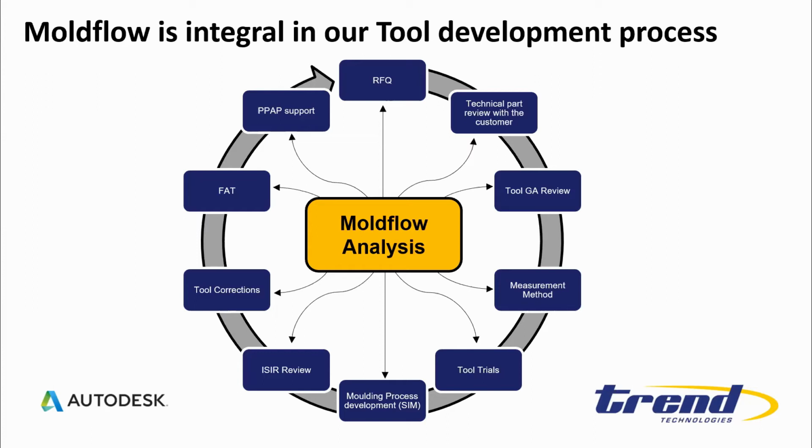Then when it gets to the next portion, developing our injection molding process and maybe measurement method, we tie in Moldflow here. We'll export warp files and check what the warpage is like, what's predicted compared with the drawing, develop our molding process within the software, and use this process as a starting point at our first trial. Rather than a process engineer having to develop a process from the beginning, Moldflow gives them a good starting point to go from, and it shouldn't vary too far from what Moldflow is predicting.